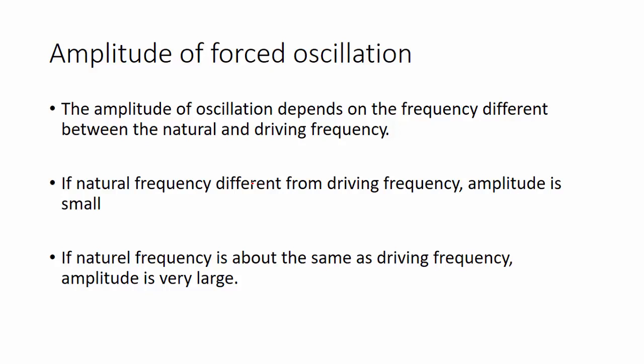Now, because of this ability to provide energy from an external force, the amplitude of vibration will also change. If the external force has a frequency that is different from the natural frequency, then the amplitude is usually very small. Imagine you're holding a pendulum that is able to oscillate at, let's say, 10 hertz, and you're vibrating at 2 hertz.